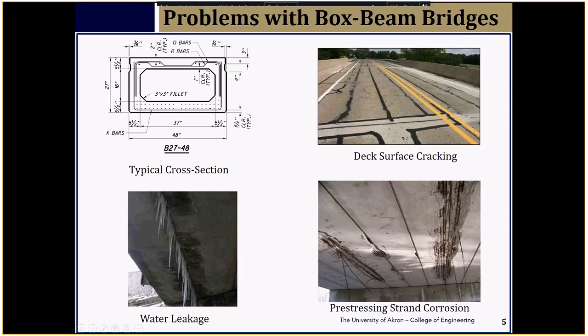Provided you have perfect alignment and there is no mismatch, things like that, and the camber is perfect on both sides, then you get 3/4 of an inch recess to fill the grout. Anchor rods are generally meant to tie the beams together, and they are tied before the grouting, and 15 kips of force is what keeps the beams together, and the grout itself is more or less a filler.